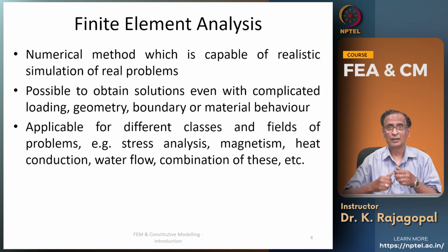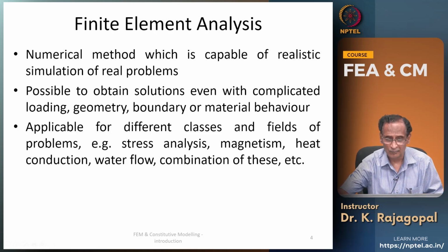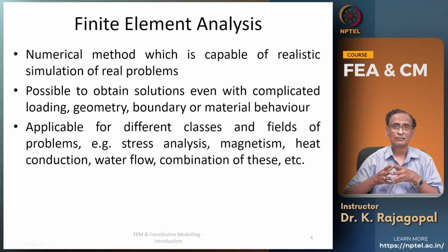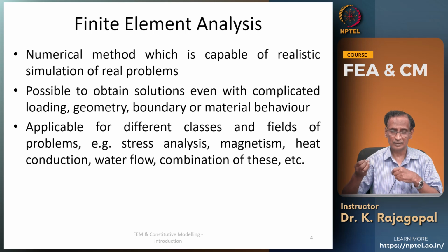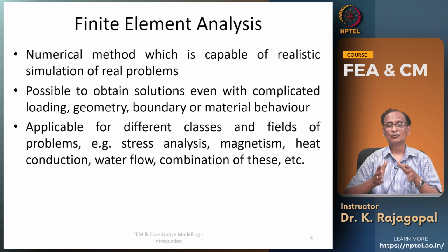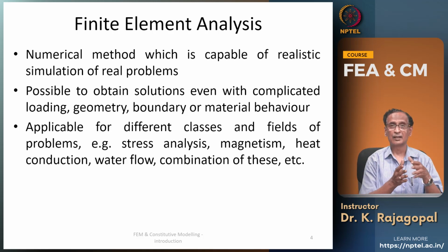And these finite element methods are applicable for different classes of problems. We can use these finite element analysis methods for doing simple stress analysis, or we can apply them in electrical engineering, or in physics like magnetism, heat conduction, and water flow, or we can combine all of them together or some of them together. For example, in our geotechnical problems, we are going to combine the stress analysis with the water.